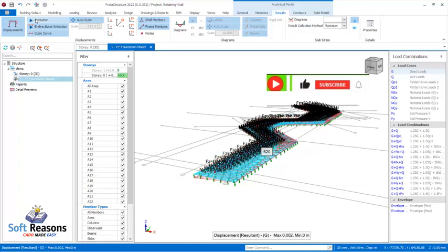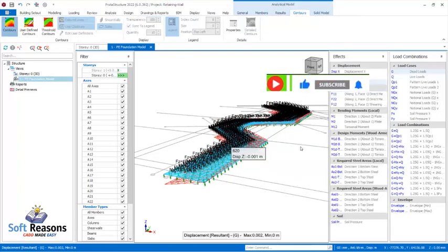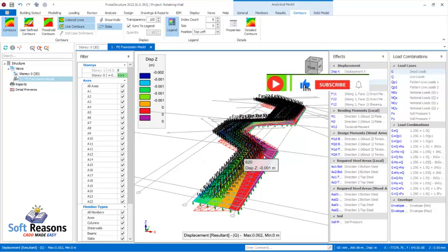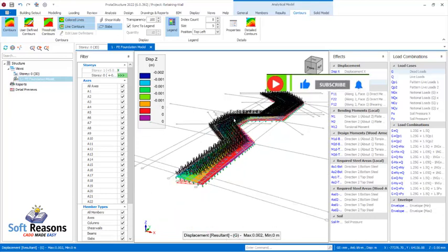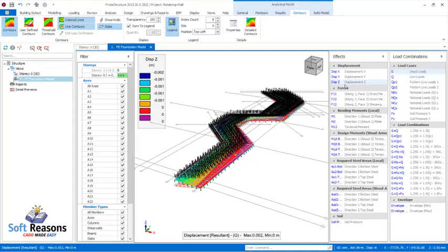So we have to get rid of the dimensions, and then I'll go to the contour options, and then I have to click on contours to contour this successfully, and also to start creating and apply the effect on this based on the forces as well as the bending moment in the local axis, and as well as the bending moment using Wood and Armer. So what you just have to do is click on the forces, which is the F11 right there, to apply this, so you can be able to read this on this legend right there. F22 you select that, F12 you select that, bending moment in the local axis you also have to select that. So all the effects have been applied on this model successfully.